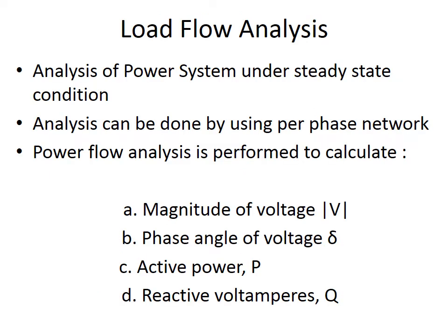The load flow analysis. The load flow study is the analysis of power system under steady state condition, that is, when the system is working under balanced condition. As the system is balanced, we can do the analysis by using per phase network. The main information obtained from a load flow study are the magnitude and phase angle of the voltage at each bus and the real and reactive power flowing in each line.